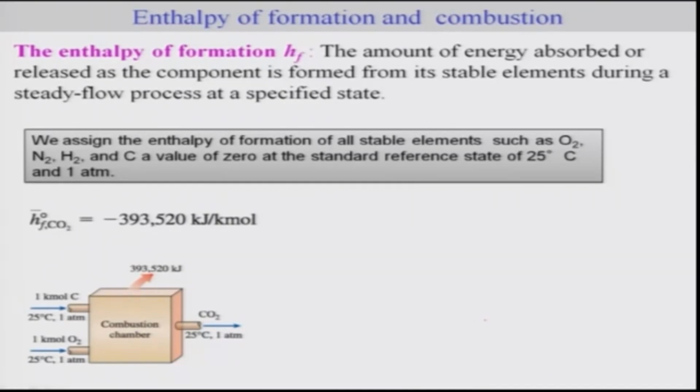This is a definition where the enthalpy of formation is nothing but the amount of energy absorbed or released as the component is formed from a stable element. So for the case of CO2, C and O2 are the stable elements. So this is the amount of energy absorbed or released as the component is formed from stable elements during a steady flow process at a specified state. A specified state could be anything. The enthalpy of formation at a typical standard state would be HF0. If it is on a mole basis, then there is a bar on top of it.